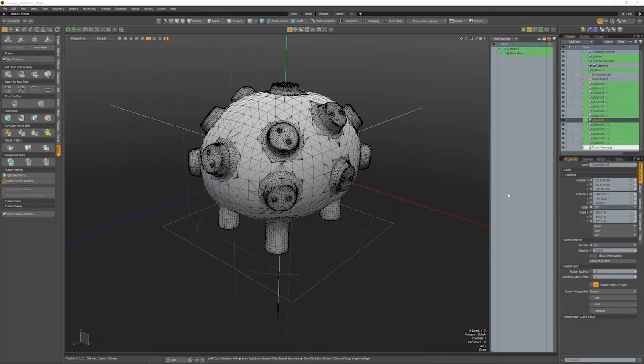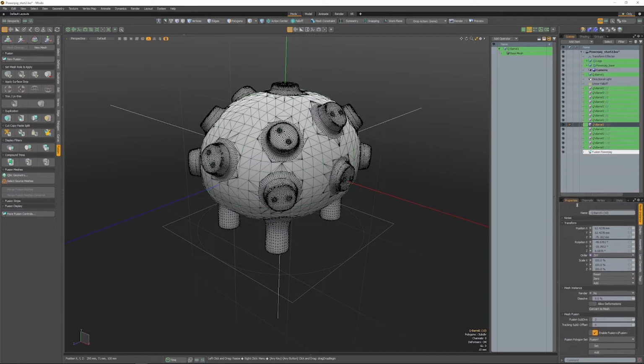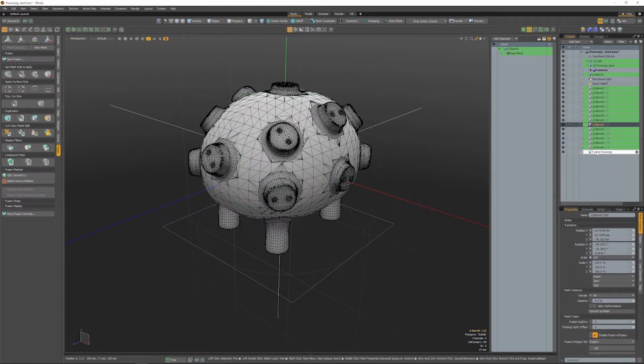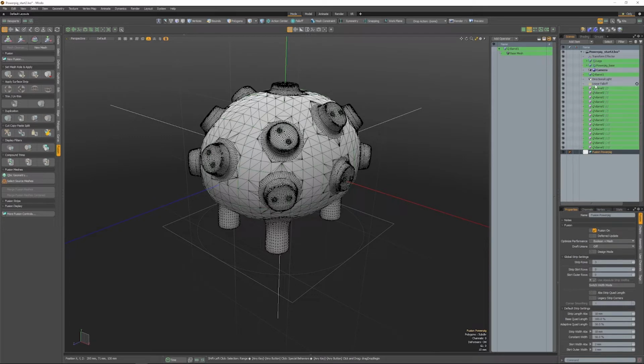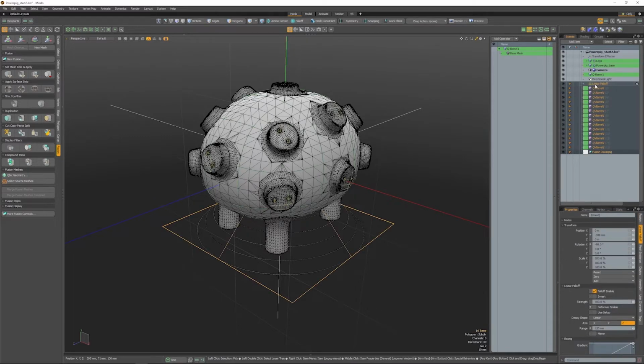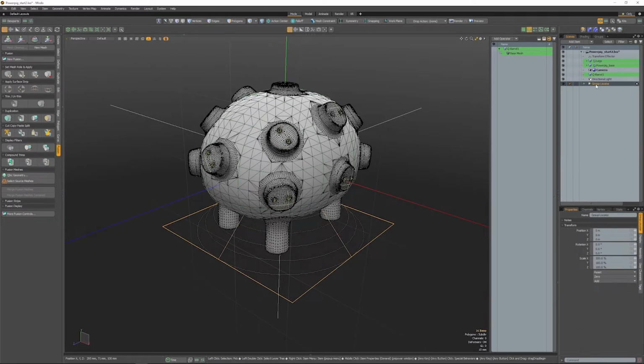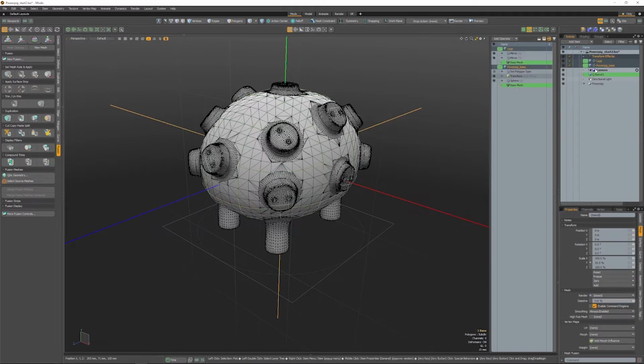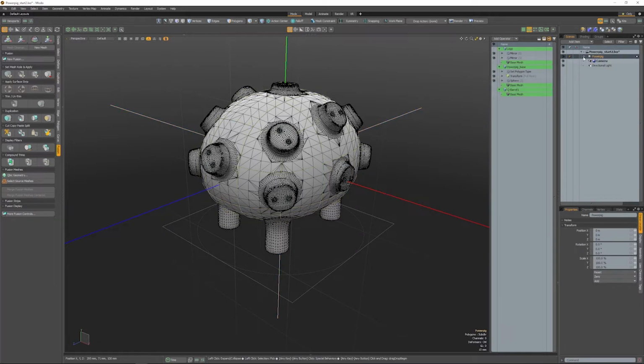So at this stage, I think it's a good thing to start to organize your scene. So I normally just start with the concept I want, and then after a certain point, I think it's getting complicated, so it's better to organize. So select everything except the lights, just the meshes, and Control G to group. Let's move this one into the group, and now put the group on the top. I normally do it like this.